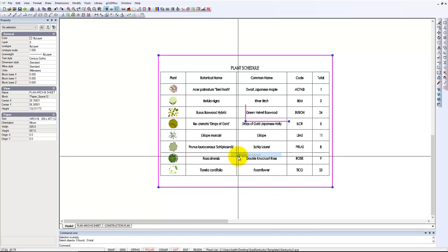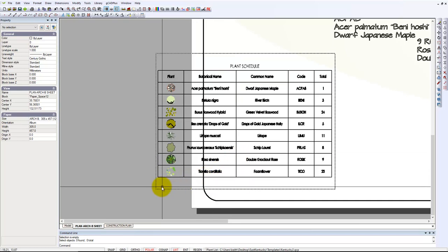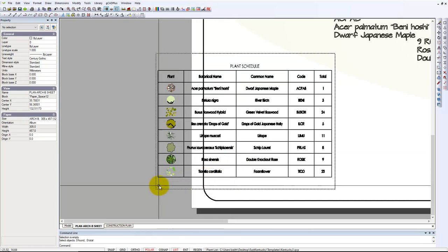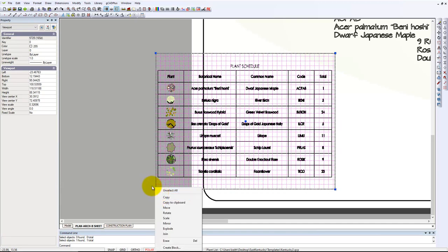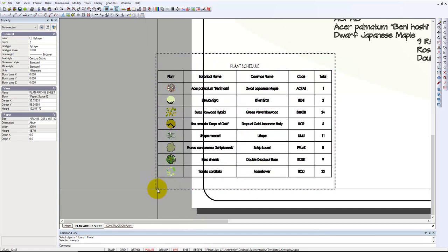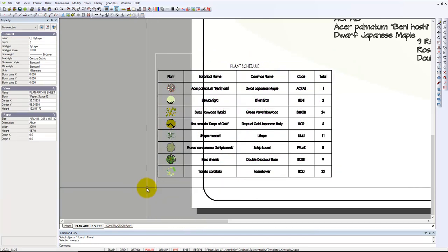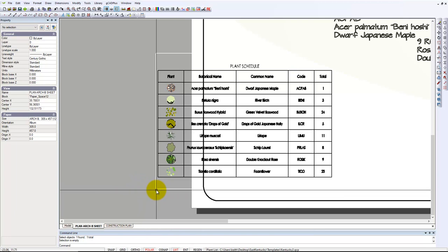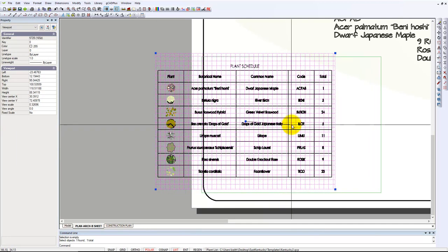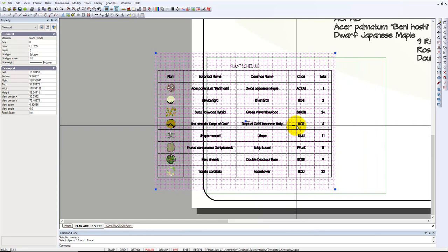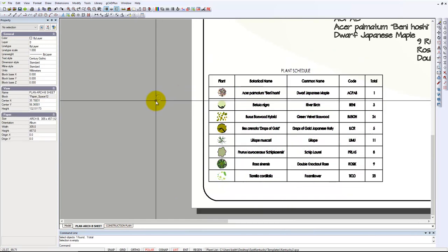So let's display that on the layout one. You can either select a crossing window through here and then choose deactivate, or better still, just double click inside the floating viewport. Now we can select it again and move it back into position, and I think that will print nicely.